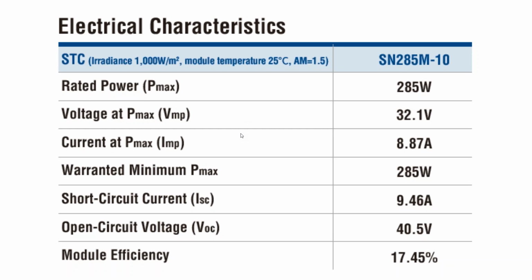That air mass thing is too advanced for this class, but basically at high noon, air mass is at a 1. And so this is saying, okay, our test is done at like 10:30, 10:45. If I wanted to see how my solar array was doing compared to its spec sheet, I might wait for the springtime, at 10:30 in the morning, on a bright sunny day with no clouds in the sky, and then go look at my production at that time, because that might approximate standard test condition.